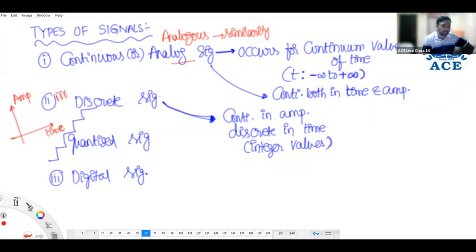Second reason, when you take a discrete signal, multiplexing becomes very easy. You are aware of mux 4/1, 8/1. Multiple signals are transmitted through a single channel. One reason we are taking discrete signal is for storage purpose. Second reason is the concept of multiplexing becomes easy. Let me explain that point, how the multiplexing becomes easy when you take a discrete signal.